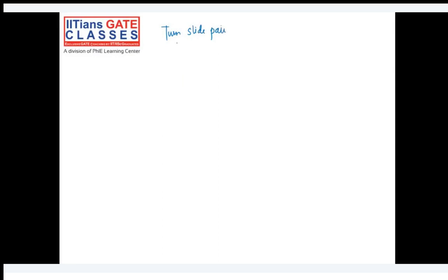I hope you understood points O, P and Q. P and Q coincide with each other in this figure, but P is on the link and Q is on the slider, and the slider is sliding on the link, and this link is also rotating, so it's a turning pair as well as a sliding pair. Let's call it a turn slide pair. This link is turning with velocity omega and angular acceleration alpha, and let's say the radius is r from this particular point.